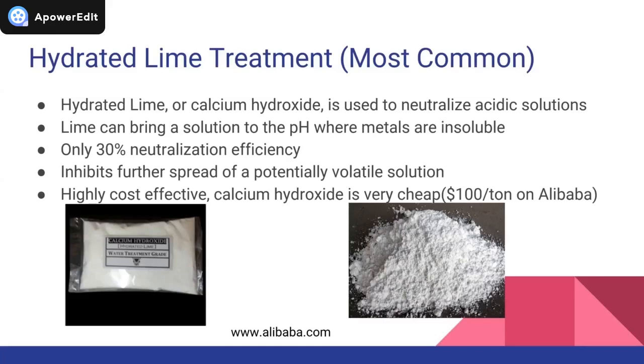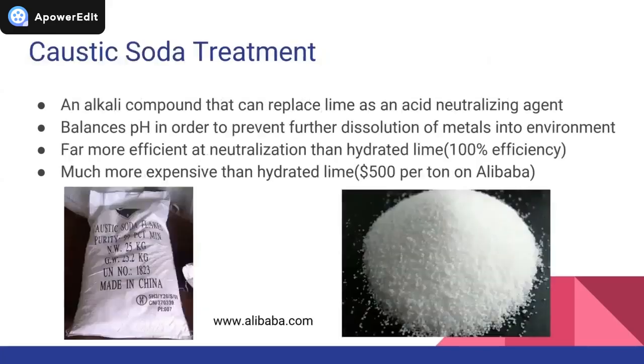And one cost estimate that I found, though, it's relatively cheap compared to something like caustic soda, which I'm going to talk about next. Caustic soda is highly effective at treating low flows in remote locations and for treating AMD solutions with a high manganese content.